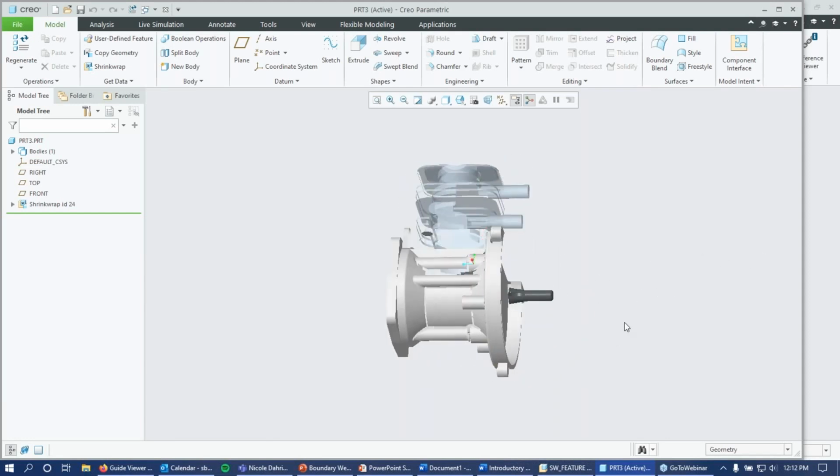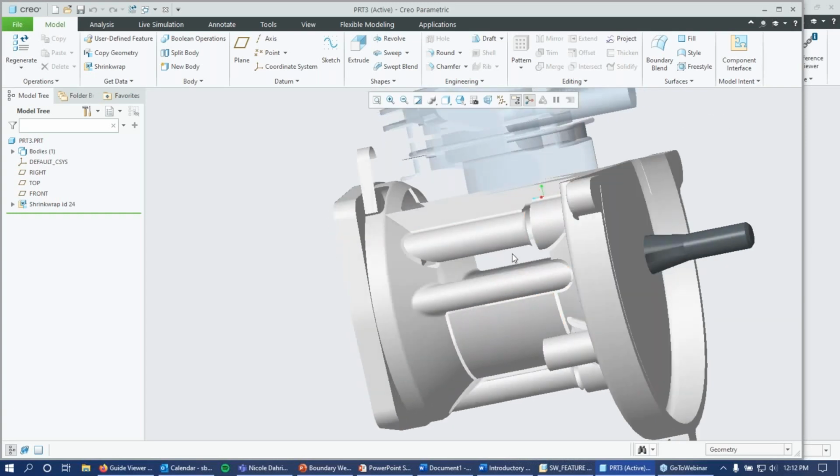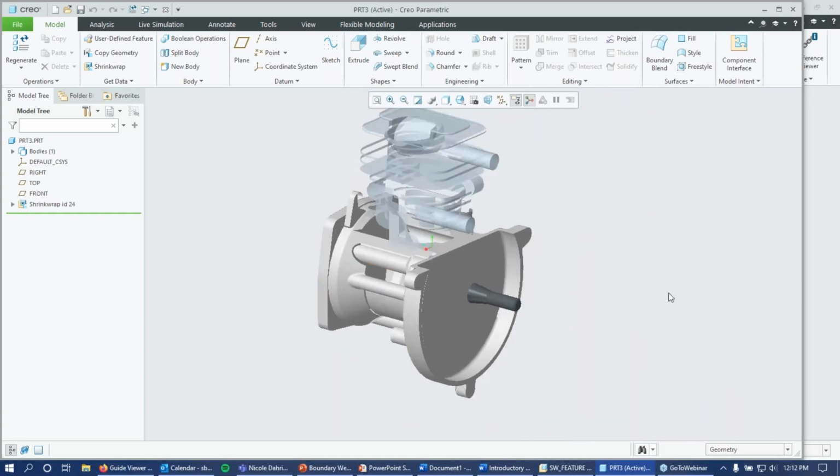As far as holes go, if you're referring to these gaps that we've got here, essentially what this will do is it'll miss some surfaces, and it won't automatically create a conjoined solid unless you choose that option to select all solid surfaces. As far as that fill holes option, what that will do is essentially try and fill holes and indentations in surfaces.